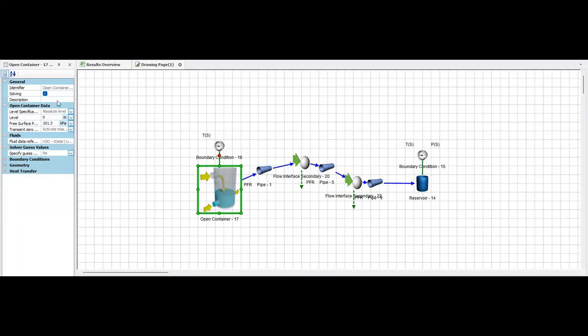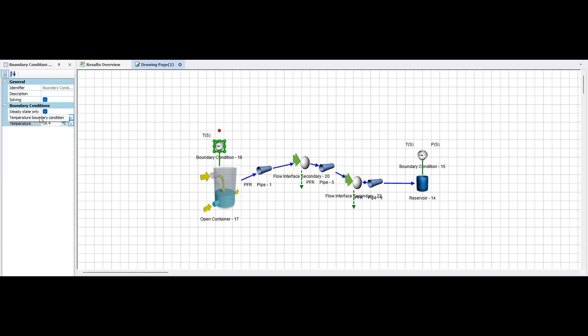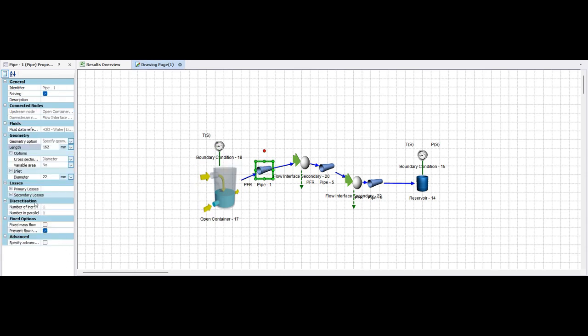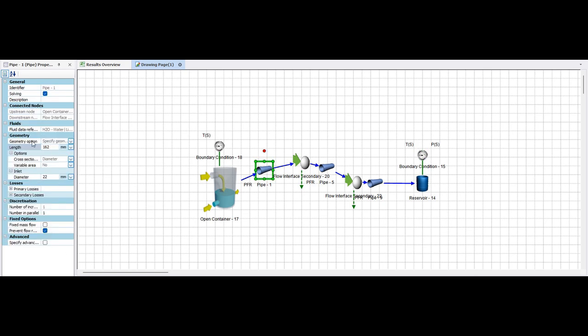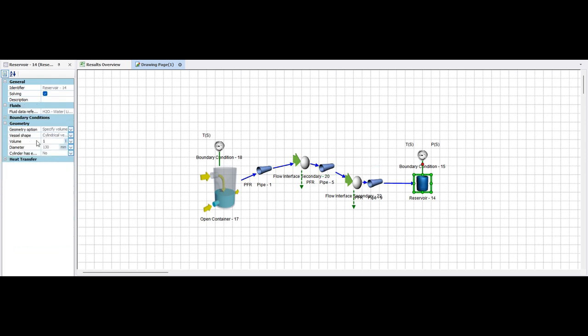Flownex was used to create a simulation for our experimental setup. The diameter and height of the bucket, along with the lengths of the expanded and contracted pipe sections, were measured and input into the software, together with the respective pipe diameters. Boundary conditions were then set based on our experimental data, including the measured temperature and atmospheric pressure. The pipe friction was assumed ideal and set to the standard value for PVC pipes.